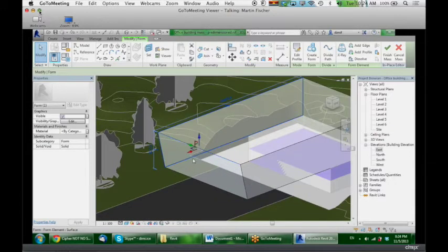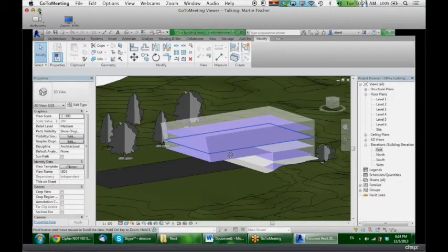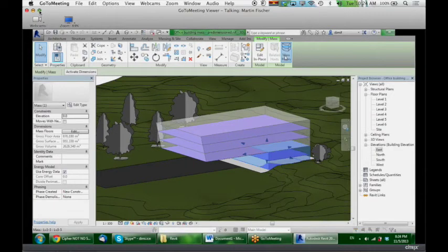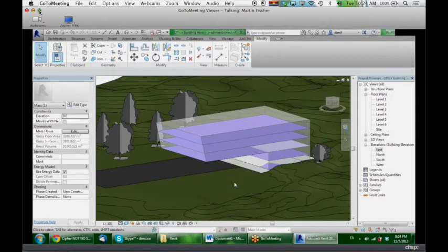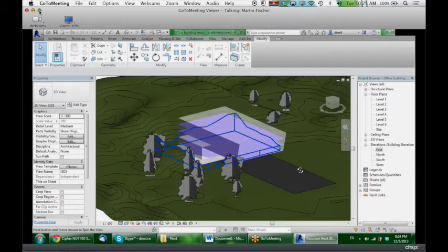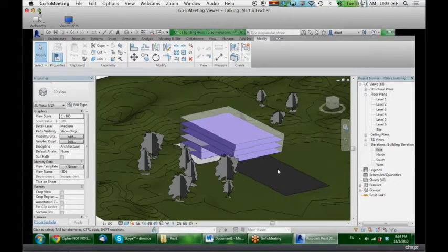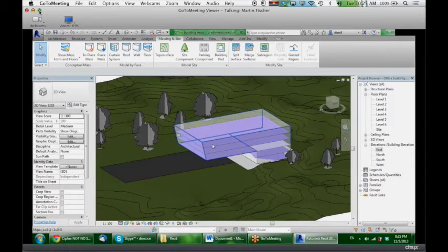And that's all there is to it. Very good. And then, again, as Glenn already showed you, for each of those masses, I just added the respective floors that reflect the levels and the elevations for this one as well, level 3 to level 6. And our design is ready. So we can start our analysis with this very basic shape. Now you can see the basic envelope and the basic mass floors.